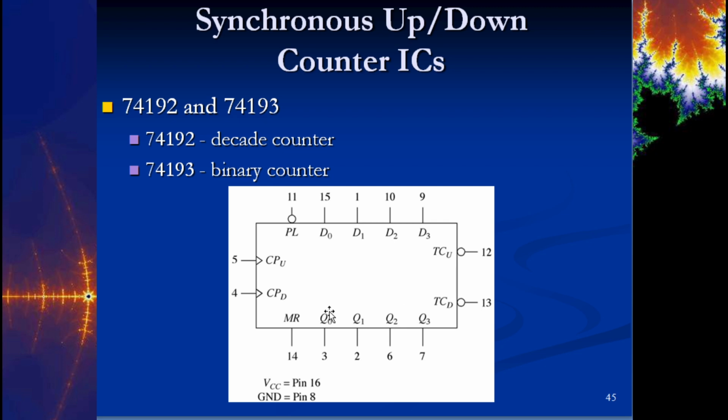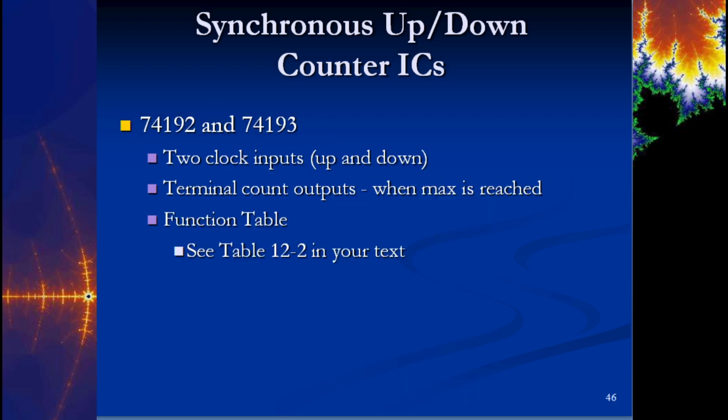So this way, it allows you to count up or down based on a simple input, and you can also parallel load something in to do a different count, so you don't have to reset it automatically here. So you don't have to use the reset. You could do what I just described. Start your count at a different number and then just continue to terminate to 15 and then load it again and then keep going. Okay, so you have multiple different ways to approach the same problem.